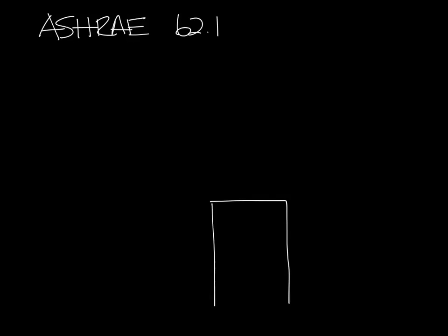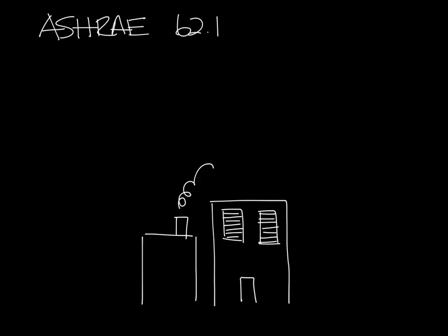So you bring in your outdoor air through louvers on the outside of the building. They look something like this. You'll see them in various locations on different buildings. Hopefully, because you want to have fresh air, they're not located near a source of contamination like the dumpsters or the loading dock. And ASHRAE 62.1 sets minimum distances from these things. For instance, ASHRAE 62.1 says you must be 15 feet from a chimney. So this would be 15 feet here. And that you need to be 25 feet from a truck loading dock. So we'll draw that over here.